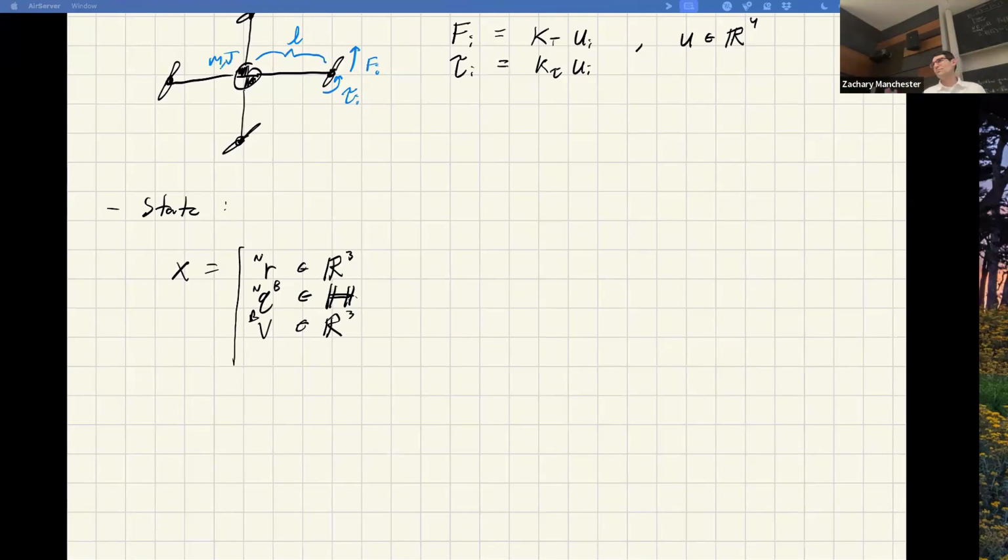Well, the IMU is giving you omega and acceleration, but you're right, they're in the body frame, and that's kind of getting at it. As before, like I kept harping on, at every possible turn we're going to choose to put stuff in the body frame, because that's where the controller lives. There are deeper group theory reasons for this, though. If I put the velocities in the body frame, that's SE3, which is the Lie group of rigid body motions, translations and rotations. And it turns out velocity in the body frame obeys those group transformations, whereas velocity in the inertial frame doesn't. There's some fancy math there, but the simple, straightforward reasoning is this: